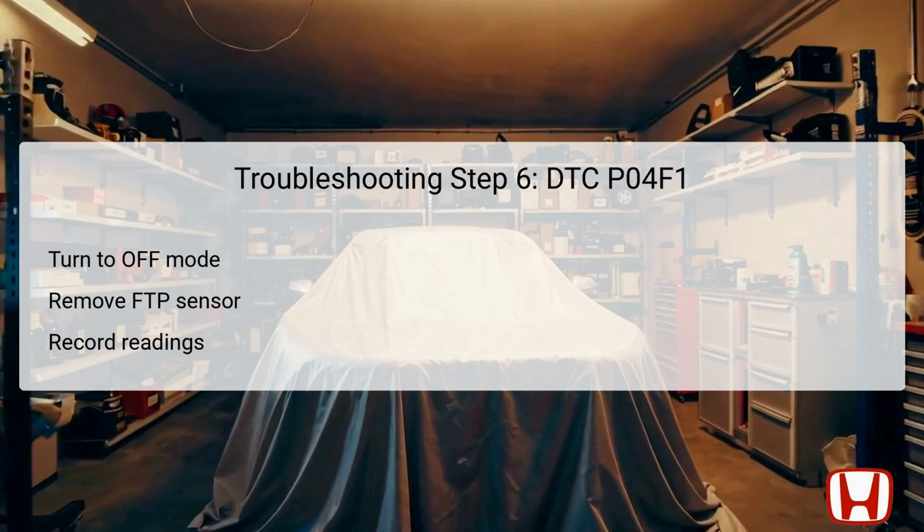This step allows connection of a T-fitting along with the vacuum pump and gauge. Turning the vehicle back to the on mode is essential for checking the operational status of the FTP sensor via the Honda Diagnostic System, HDS. Record the readings from the sensor in the data list provided by the HDS. This data will showcase the sensor's performance and any deviations from expected values.